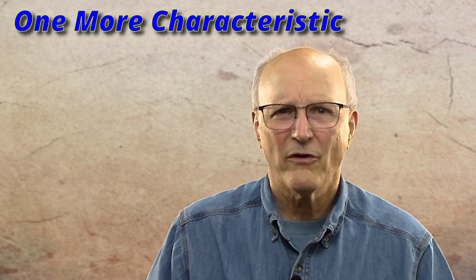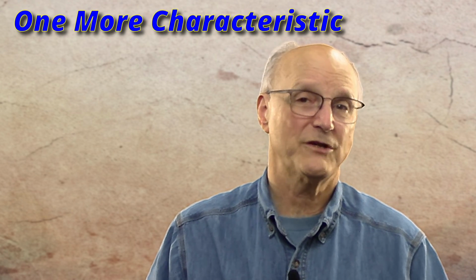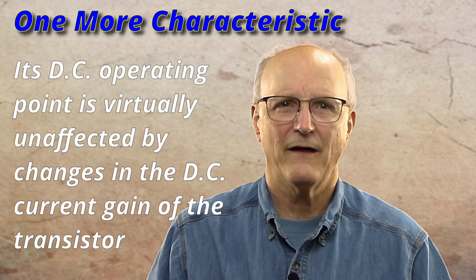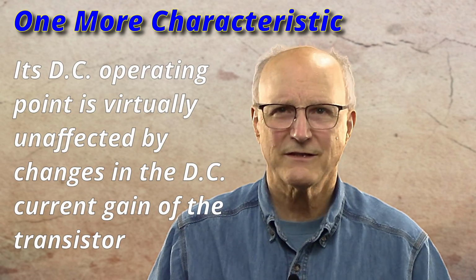The good news is that this configuration is by nature very stable with regards to changes in the DC current gain of the transistor. This is because the common base configuration does not provide any current gain and is thus not affected by changes in the DC current gain of the transistor. So I suppose we should add one more characteristic for this configuration. Its DC operating point is not dependent on the DC current gain of the transistor.